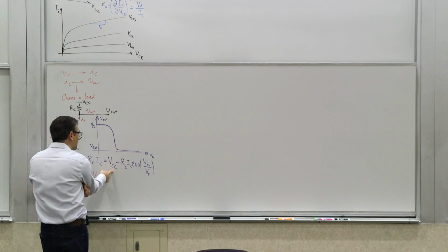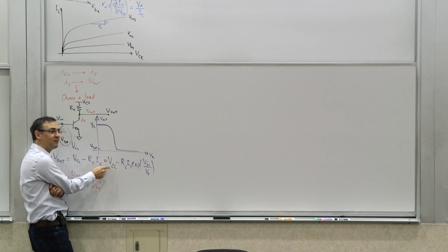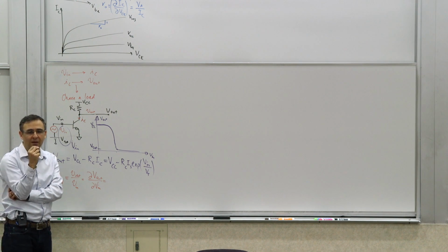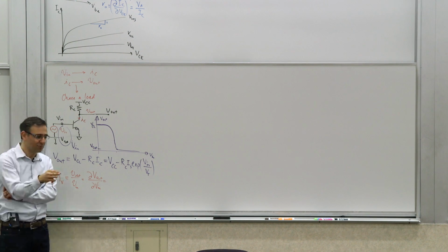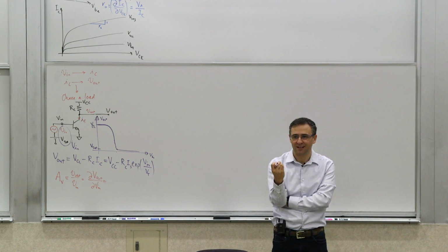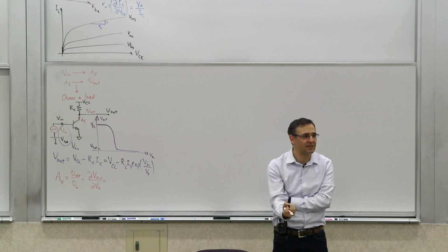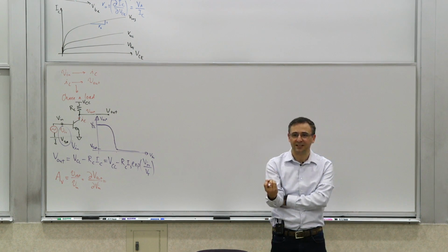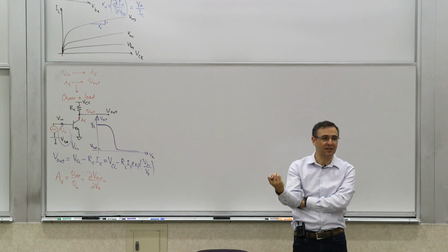Well, the derivative of the first term is 0. It's a supply. Now, this derivative being 0 is important. Another way to think about this is that all DC supplies, and listen to this carefully, because we see this more frequently than we would like to in your homework problems, not this year so far, but I'm saying that generally, any DC supply from an AC perspective, from a small signal perspective, from an incremental perturbation perspective is what? It's a derivative of the DC. 0.